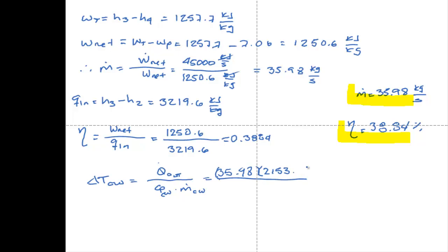This number comes from subtracting H4 minus H1, that we are indicating right now. 191.81, and we divide this by the product of Cp, which we already stated is 4.186 times 2000, and this temperature rise is 8.4.